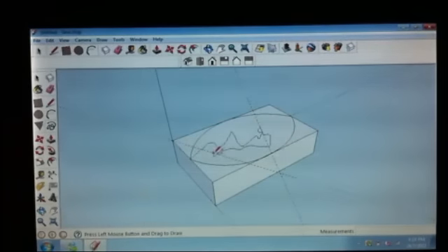But beware that you cannot cross lines in Google SketchUp. When you cross a line like this, it is not recognized because you cannot get the shape out of it. So when you are using a pencil to draw, you have to control your mouse quite well. I will demonstrate this to you later. Let me Control Z again to undo this whole thing.